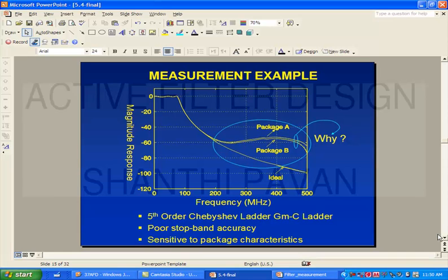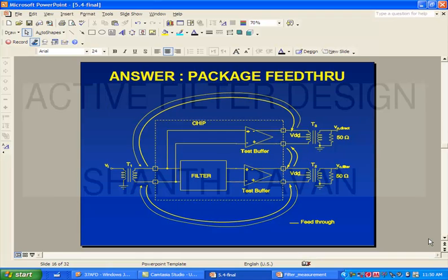So there's some inaccuracy here. The reason for that is that, as I said, this IC is mounted in a package. So there are actually inductors going from the pads on the silicon die to the pads on the package. These are basically many gold wires going from point A to point B, all parallel to each other. So at high frequencies, what is happening?